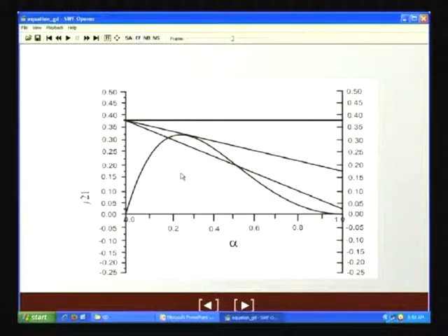So, what do you get under these particular situations? From these situations, we find that below a critical value of alpha, you have 2 points of intersection. That means, for counter current flow with gas up, liquid down, there can be two possible flow patterns where the flow can be stable. One is at low alpha.